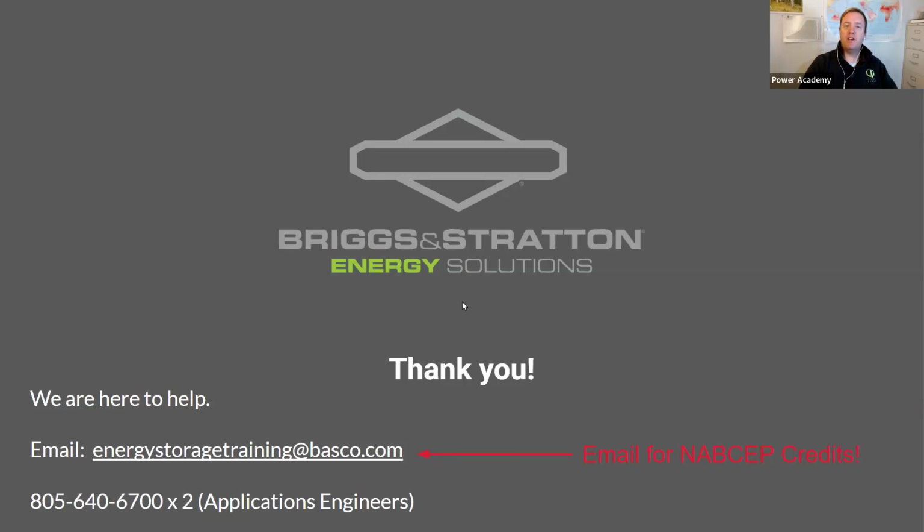I love it. And Nathan, any final thoughts from you? I guess one thought that came to mind is one other limitation on battery system sizes is code. Daniel, you do a nice talk on codes and standards, and in most locations you're limited to 80 kilowatt hours. So your garage, or the outside of your house, you can have 80 kilowatt hours maximum there, in stacks of 20.